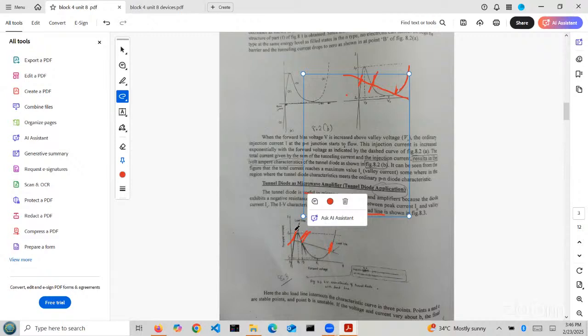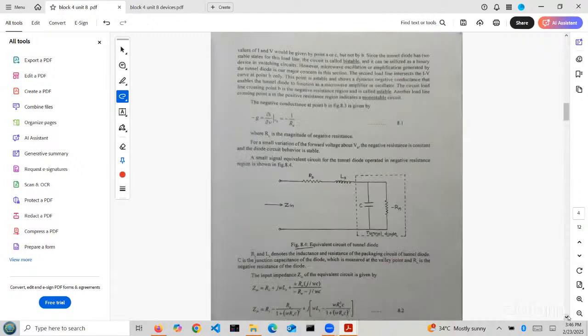Same way, draw another 2 load lines, one is represented as astable, another one as monostable. Total 3 states. In general, a flip-flop is a bistable multivibrator. So from this, we are discussing which is astable, which is bistable, which is monostable. After drawing a load line, A and C positions are stable points, whereas B is an unstable point.